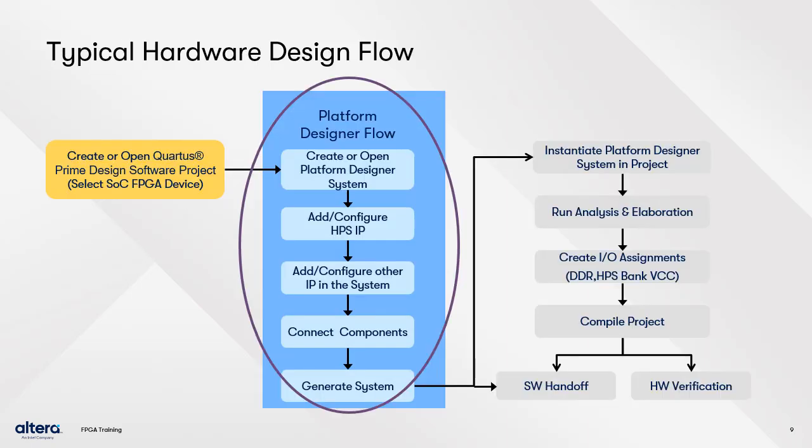This is the complete Quartus Prime software and Platform Designer hardware design flow for use with the SoC devices. On a high level, you start with a Quartus Prime project or open an existing one. Then, within the project, create a QSys system that instantiates the HPS, custom IP inside Platform Designer, and other off-the-shelf IP available from Altera or third-party vendors.